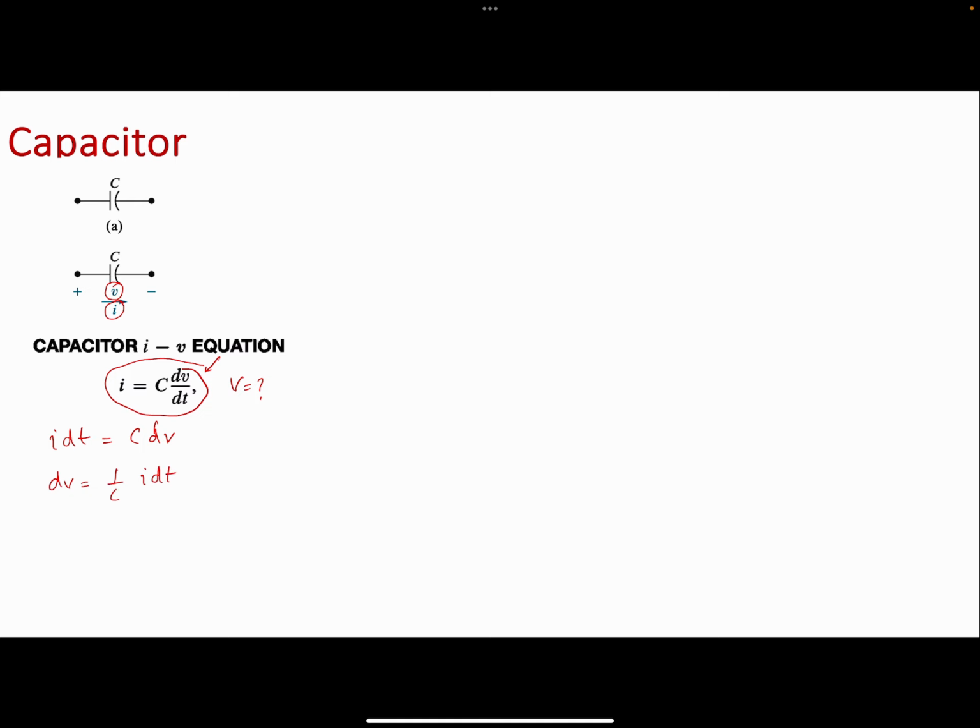Again, we are going to do something very similar, where we replace the variable of integration and move the limits of integration onto other variables. For the voltage, the limit of integration goes from 0 to some time t. The integral of dV equals 1 over C, and time goes from t naught all the way to t, of I times d tau.